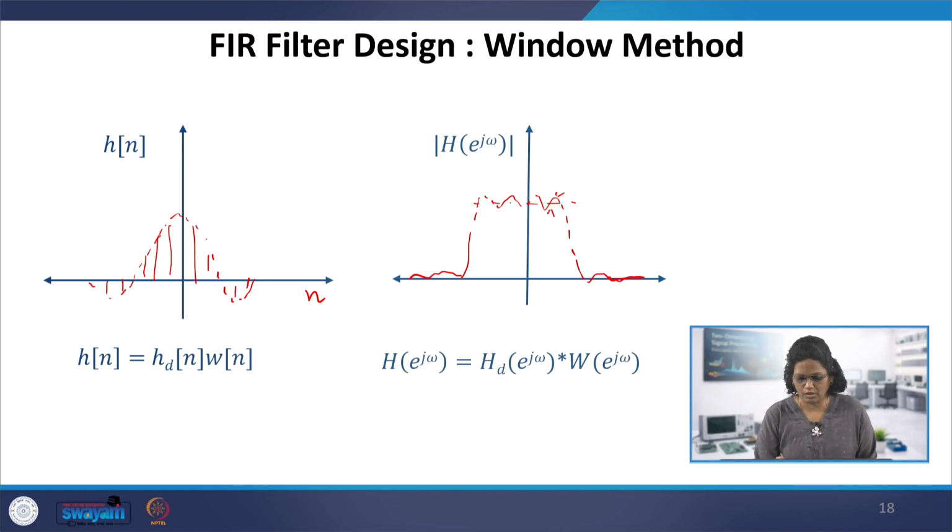So we will not have the ideal magnitude response as desired. It depends on the number of coefficients. If we have more coefficients, the order increases, and the cutoff region, the transition region, becomes smoother and smoother. So here is the passband frequency, this omega, and this is the stopband frequency.